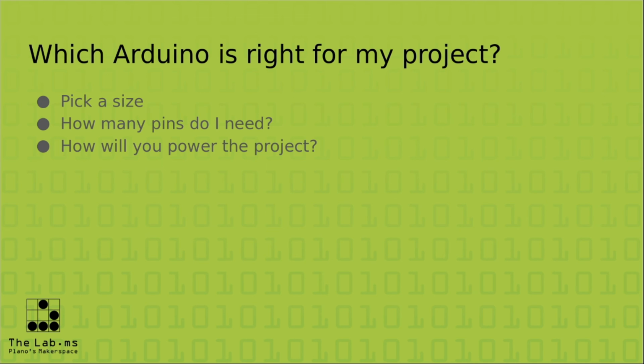So which Arduino is right for my project? First, some of the main factors that you need to think about are size, how much input-output you're going to need, and how you're going to power the project. This isn't an exhaustive list by any means, but these are probably some of the first things you should think about when trying to figure out which Arduino you should get for your project.